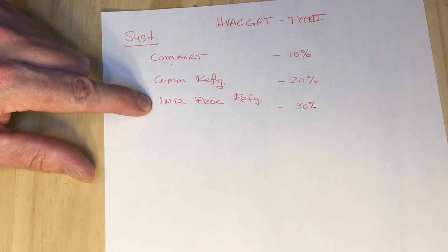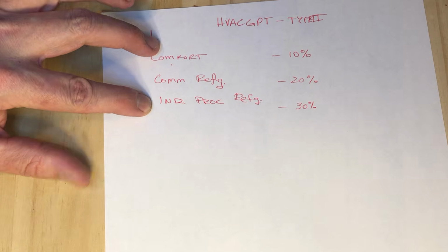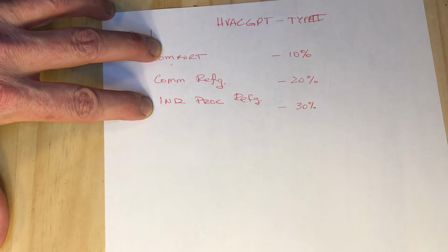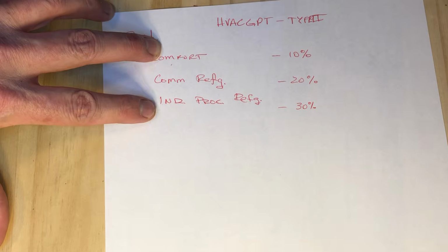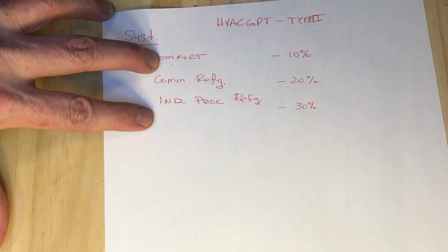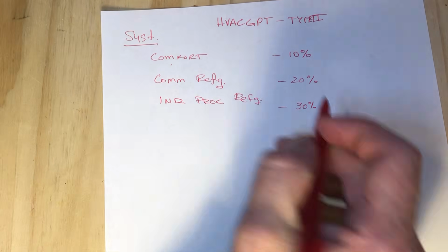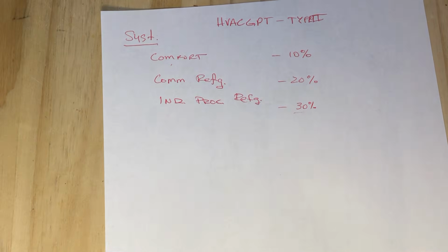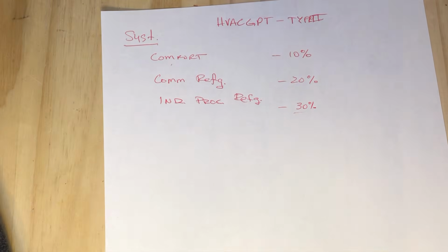So if you had a system that was 65% industrial process refrigeration and they ran some water off of it to maybe work some fan coil units for the other 35% of coolant, if it's 65% over here, then that's going to be a primary industrial process system instead of a comfort system, and it'll fall under these leak repair requirements if they're drawn from the same. You go with the majority of the system that you're there.